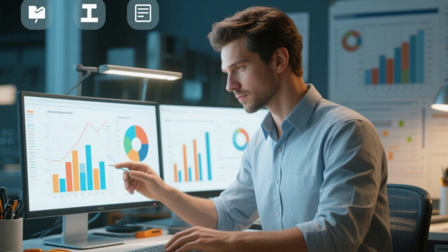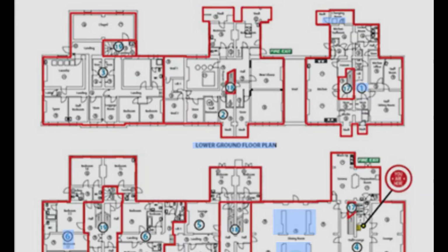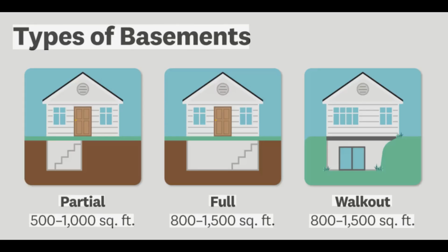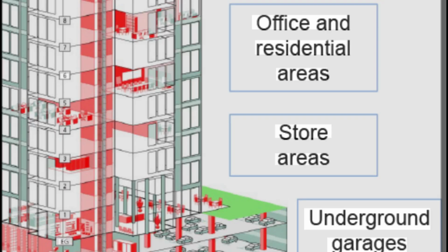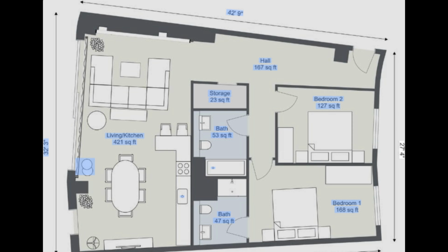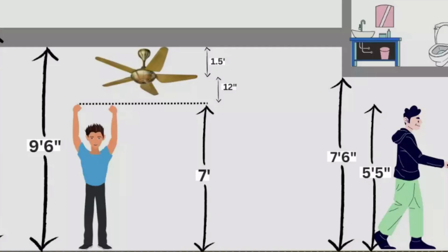1. Architectural inputs. You must collect number of floors, number of basements, floor area per floor, total built-up area, building height, RDF, ceiling height, layouts of guest rooms, corridors, kitchens, and storage, shaft size and location, false ceiling height. These give you the physical constraints and guide the pipe routing strategy.